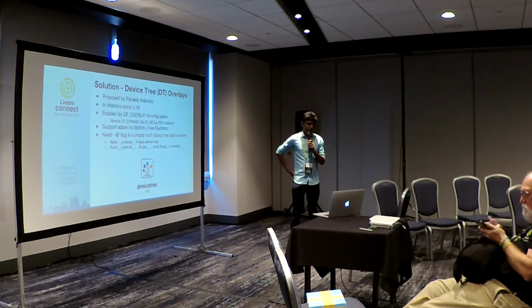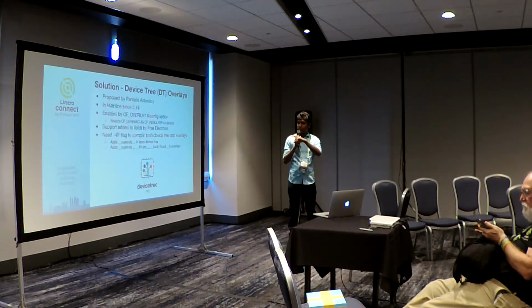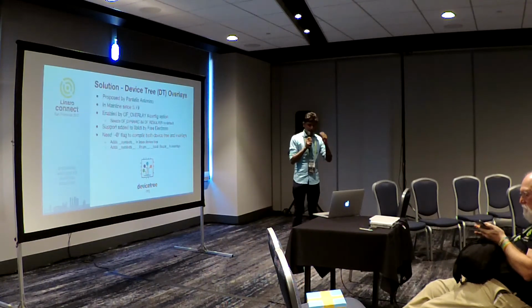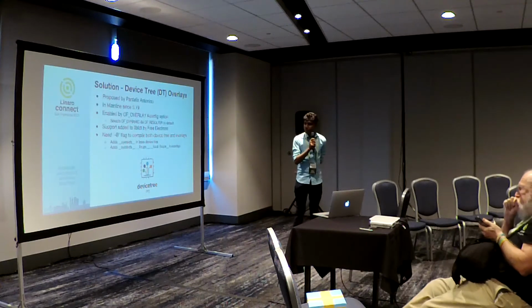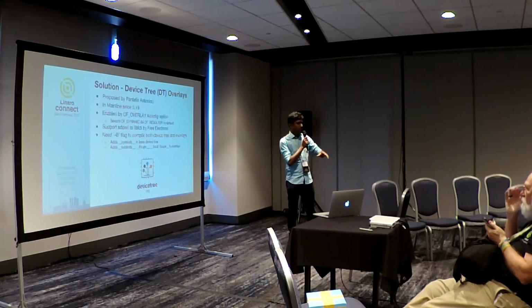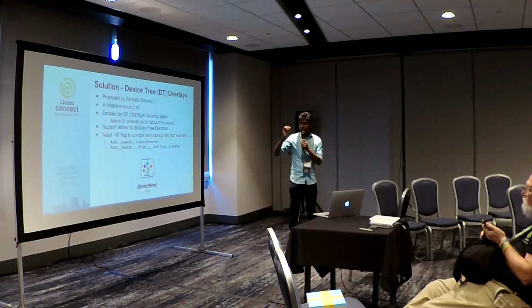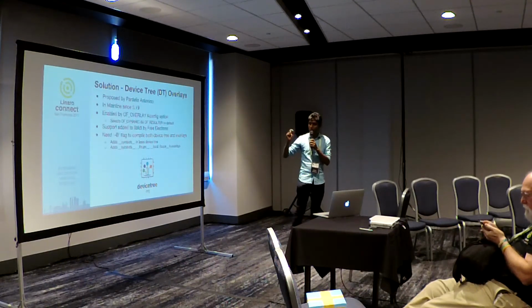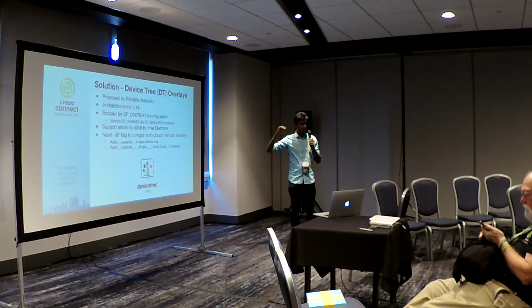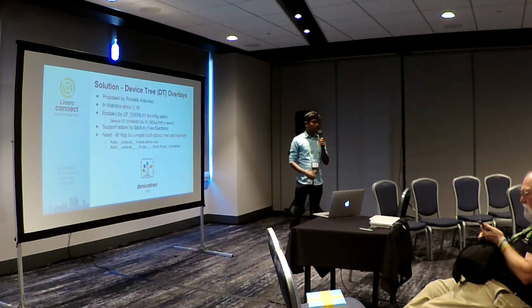Free Electrons, one of the interesting companies, actually added the support for device tree overlays in libfdt, which is headed by David Gibson, I guess. What they wanted to do was enable the device tree overlay handling across the board. Right now, the device tree overlay methodology has been implemented in the Linux kernel, before Free Electrons' involvement. They wanted that methodology to be present in libfdt, which is part of the device tree compiler, so that any project other than the Linux kernel can benefit from that. So they added the support, Maxime Ripard added the support, I guess.